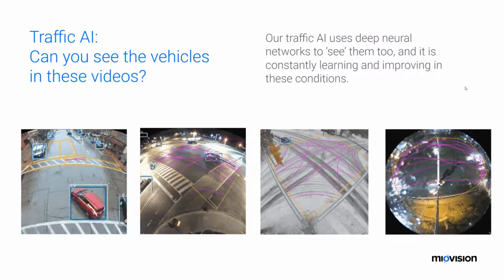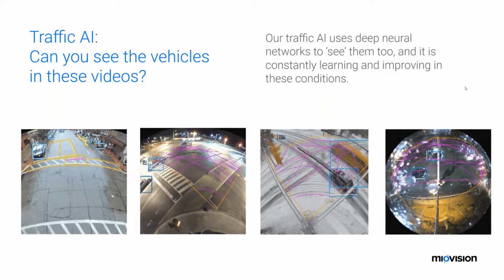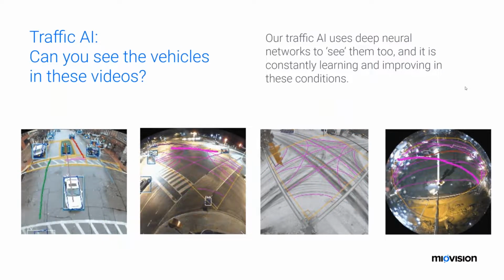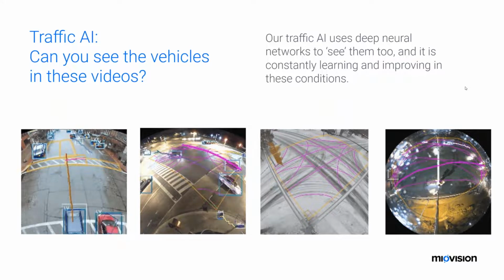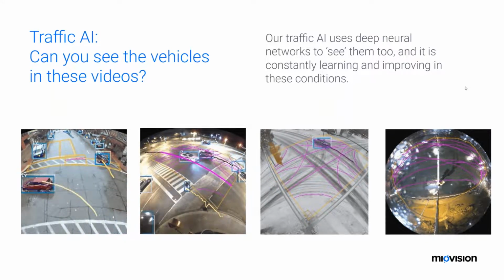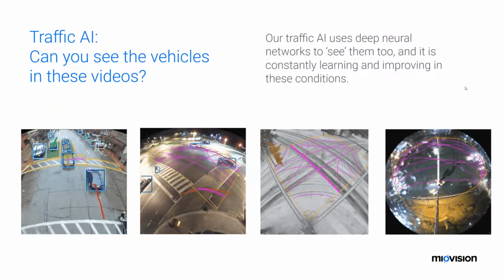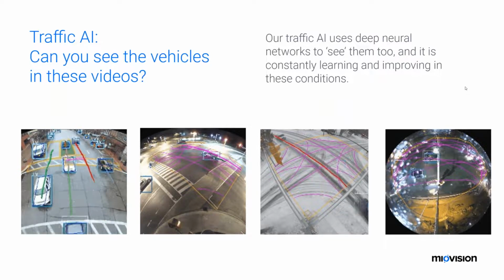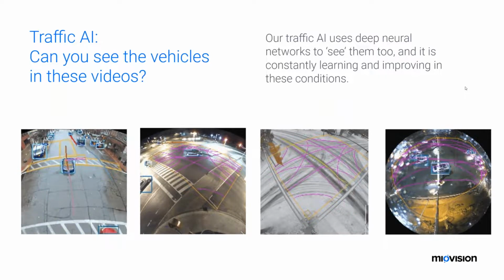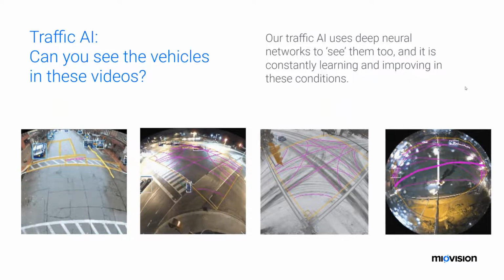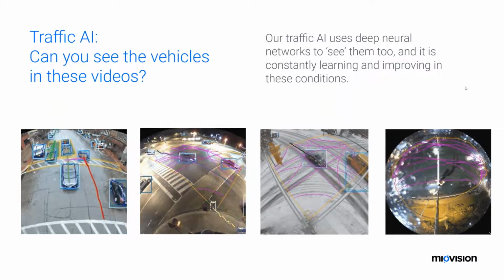And I think understanding that video detection had its issues. However, technology's come such a long way since then, and obviously so has the performance of video detection. We've used all of that data that we've captured in an AI algorithm to actually model what vehicles look like, including cars, buses, trucks, articulated trucks, pedestrians, cyclists. So instead of using background subtraction, we actually look for the characteristics of a vehicle, and as you can see, a square box goes around them as they move through the intersection, and we track the movement.